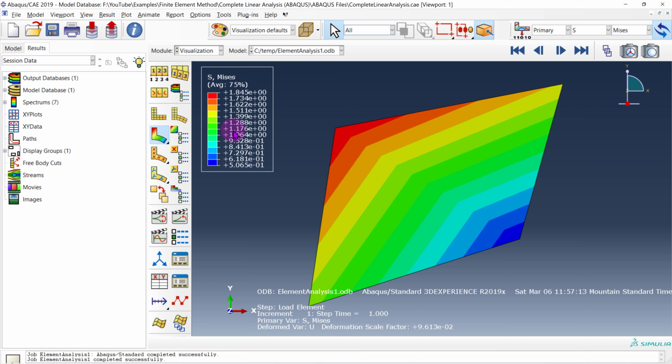So now what we're going to do is take those results that we had in Mathematica, and directly compare them to our ABAQUS results. Two of the most important things that we solved for off the bat were the nodal displacements as well as the reaction forces. If I want to look at my nodal displacements first, I go up to this property over here, and this is basically what is being plotted. By default, it's on stress, and more specifically, the von Mises stress.